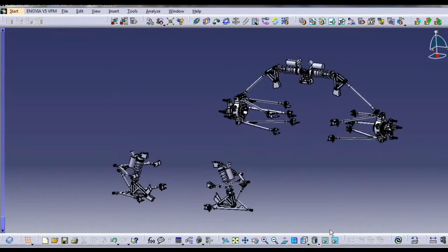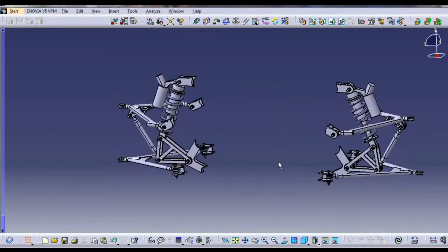After the rear suspension system, let's move on to the front suspension system. At the front suspension, we used pull rod geometry. The reason was that with pull rod, we get more downforce in the front of the vehicle. This helps us to balance the weight distribution of our vehicle, because as the engine is situated at the back, the weight at the rear section is more.